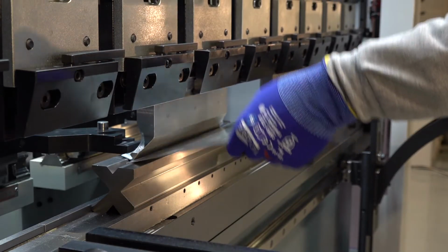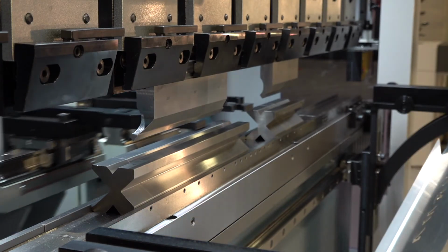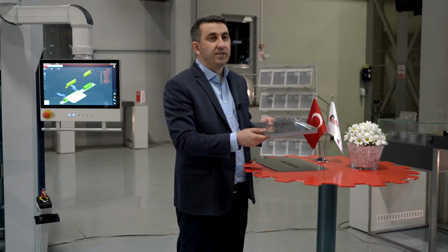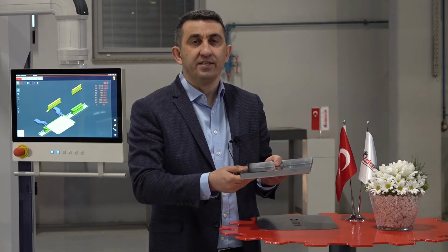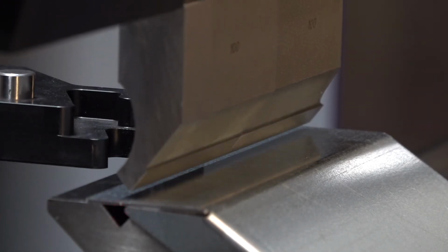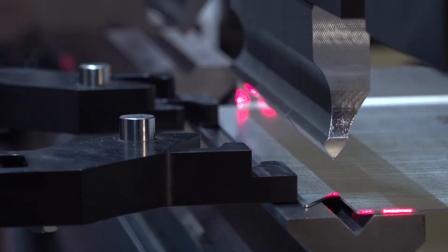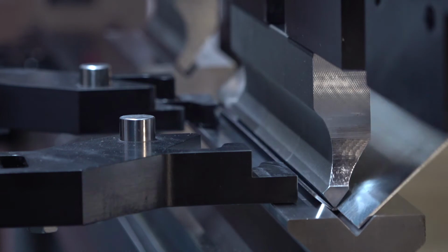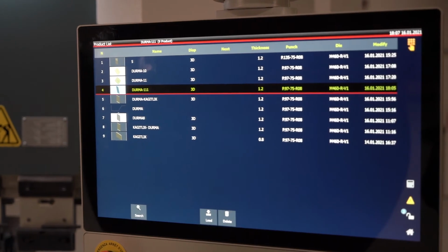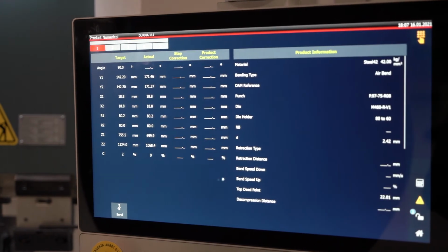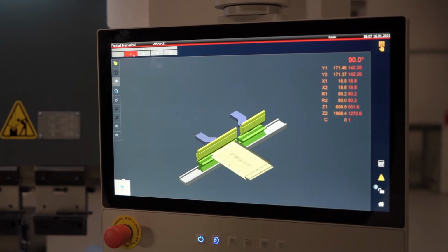As you know, the part to be bent can be ST37 sheet, galvanized sheet or stainless steel. As a result, the elongation coefficients of materials will vary. There will be different radius sizes depending on the features of the punch and the V-channel clearance of the tools we will use. In our SKY22 control unit, all these errors will be eliminated with the 3D import feature and automatic tool bending sequence features.